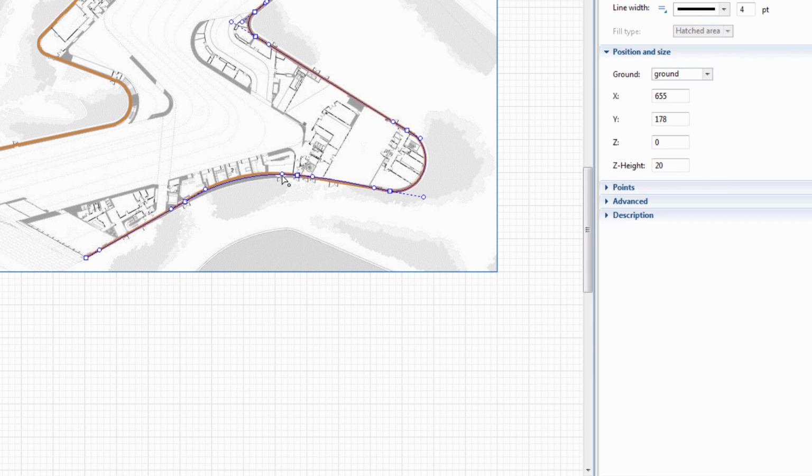The guiding lines on the sides of each point are interconnected. By moving one point, you move the other point as well, adjusting in this way the curvature of 2 segments. To move a single guiding line, press and hold the Control key and then drag the marker. In the same way, adjust the endpoint of the curved segment.